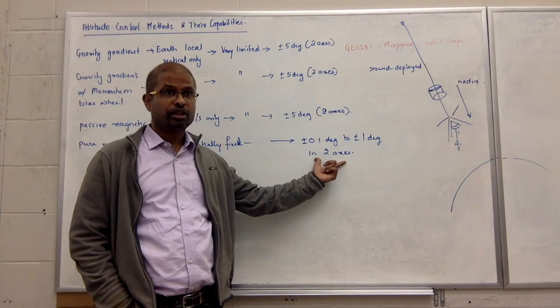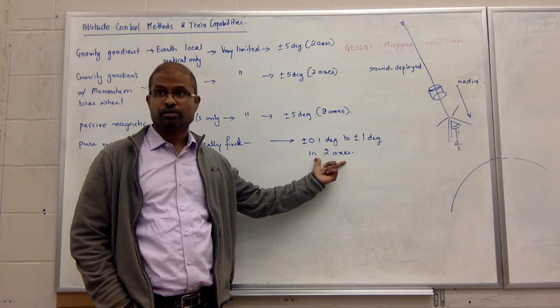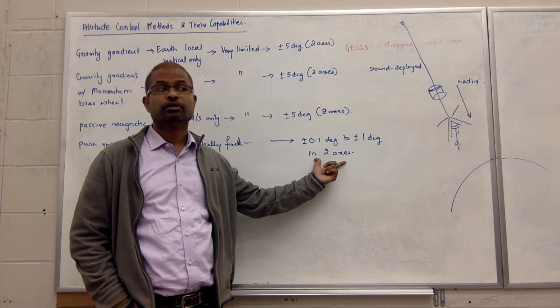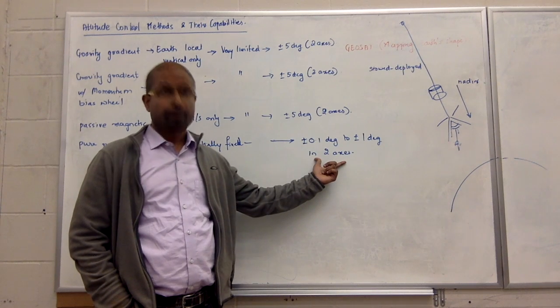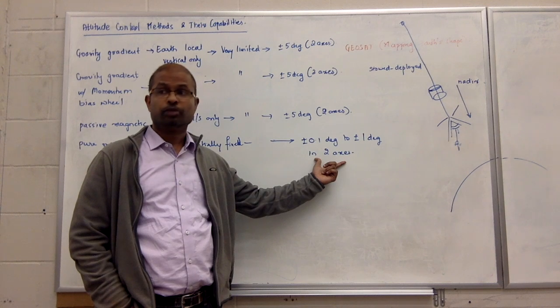The accuracy is good if you design really nice wheels, and this is again an area of spacecraft engineering you can pick up: designing very nice wheels. What is the issue with wheels? Friction is an issue with wheels. Particularly in space, you cannot use lubrication.